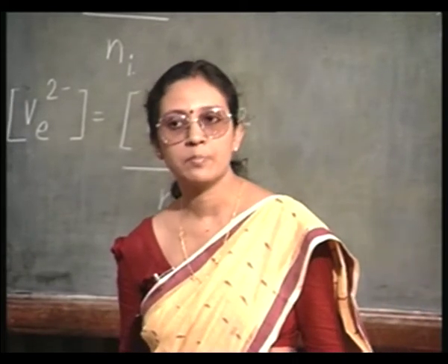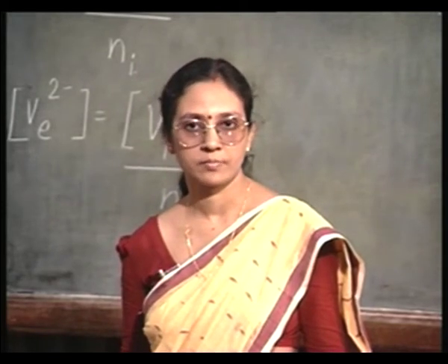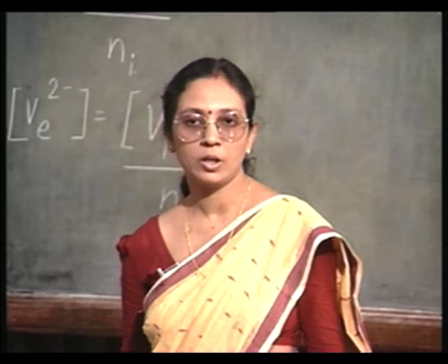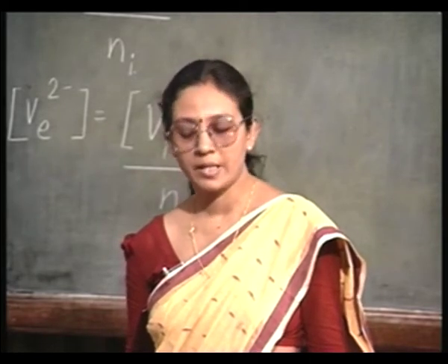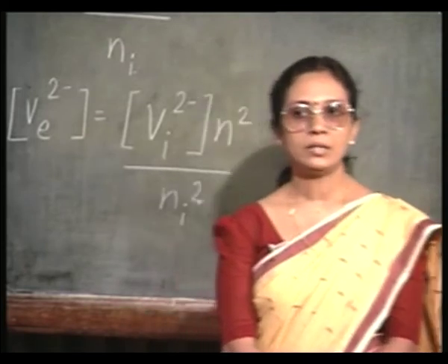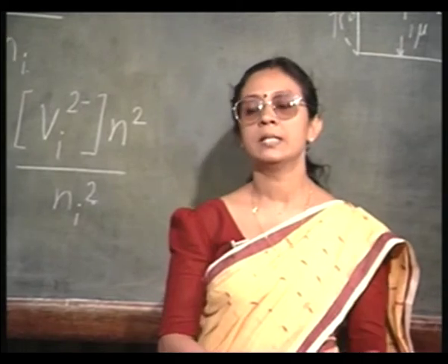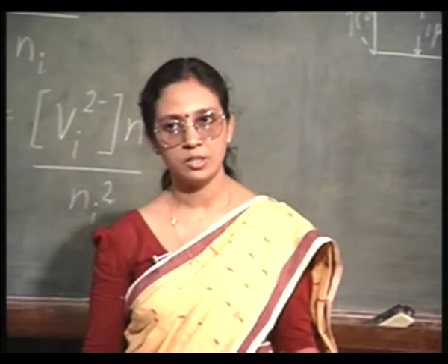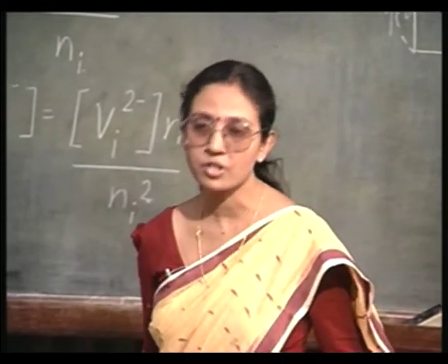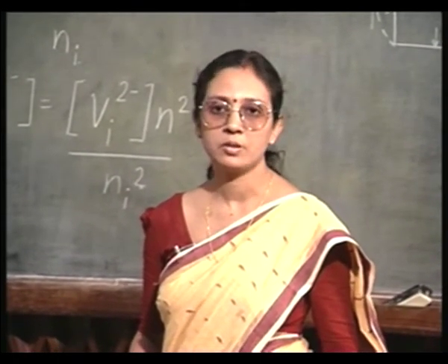Dopant sources can be solid, liquid, or gaseous. They all have their various merits and demerits. But one thing is common, that in most cases the basic reaction is between the oxide of the dopant and the silicon.